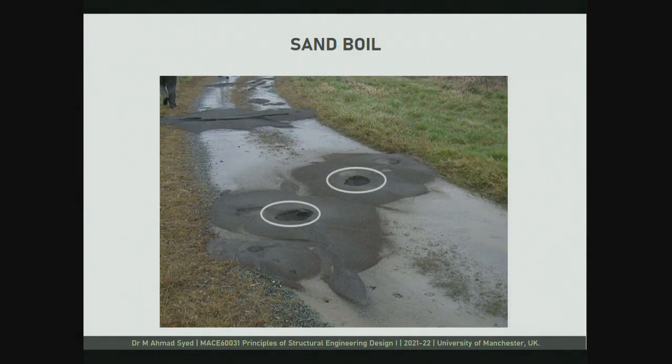So if you happen to do a reconnaissance survey as an aftermath of an earthquake as geotechnical engineers or structural engineers, if you notice these types of things, then it is a very important precursor to liquefaction. You can clearly identify that liquefaction has taken place. You will have granular soil mass at the surface, you will have water, and you will have these typical crater type, central dome type structures.